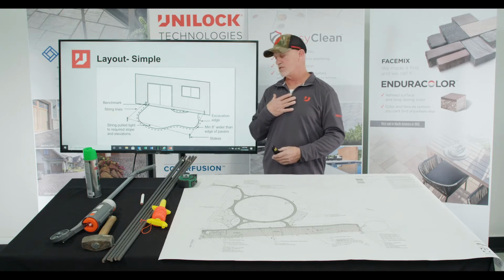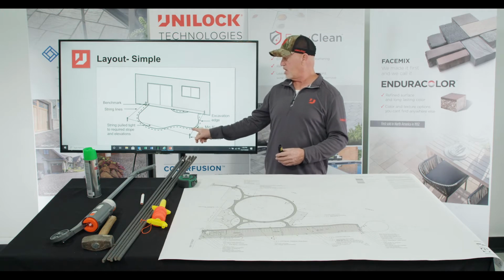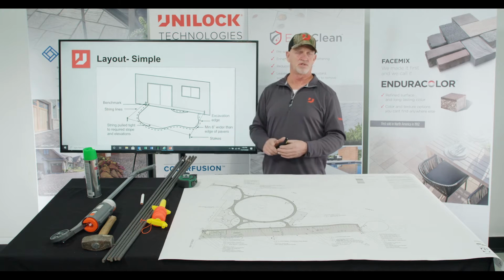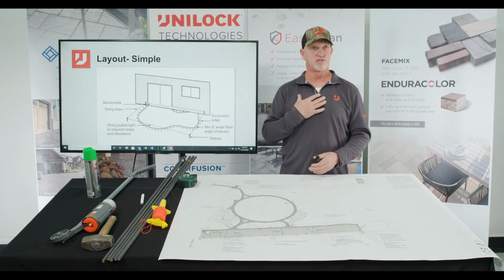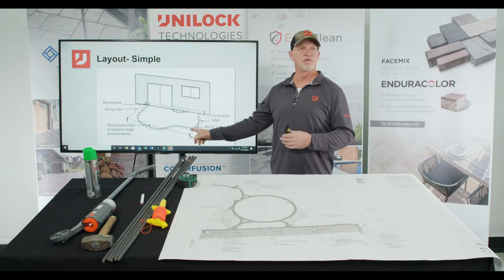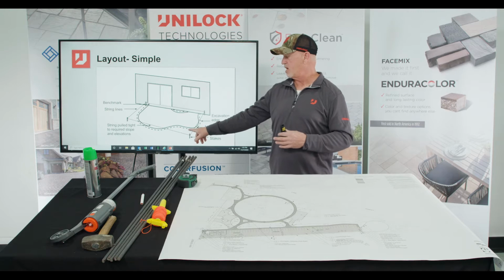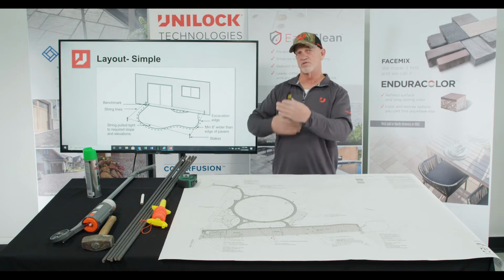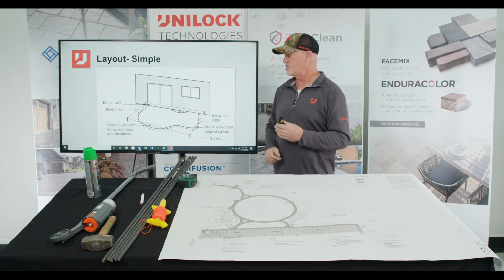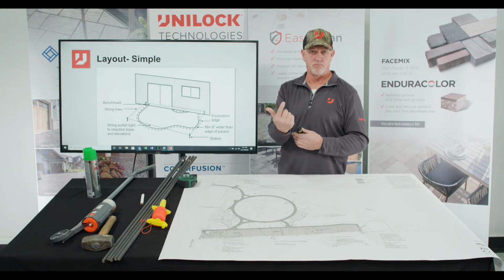One of the things I like is they've done a hard paint spray here on the interior edge, which is the paver edge, and then they're doing a dash line on the exterior. I also like that, both lines. However, at this point in the installation, I'm more concerned about laying this material out and having a hard line here on the exterior. So my technique is almost the reverse of what you would see here. But the important thing is that we've got an identifiable benchmark.